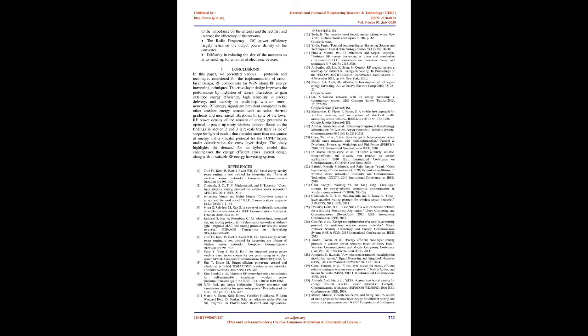Mansard et al. 2018 proposed an exponential rectifier, DR, designed for producing energy from radio frequency with a power of 0 dBm. They propose to increase the efficiency over different frequency ranges with reduced size of RF rectifier circuit. The topology claims to provide an efficiency of more than 30%. Also, the proposed topology claims the PCE more than 30% over a wide range of frequencies from 950 to 1500 MHz. A commercial balanced unbalanced, balun, component is used for port transformation. The design claims to work for varying carrier frequencies with PCE of 57.5% at 1.1 GHz.